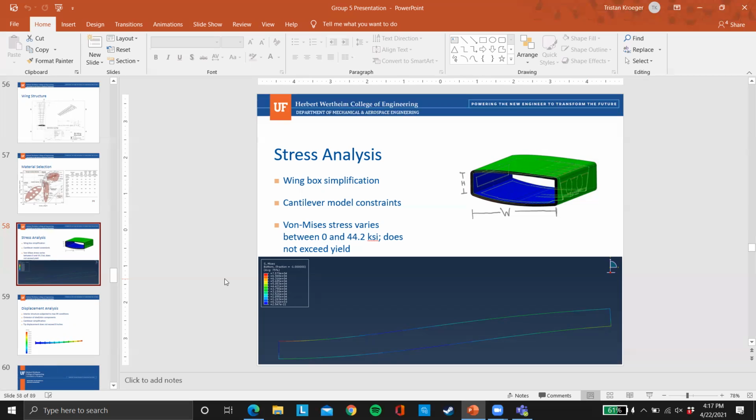Yeah. So now let's say this is the fuselage, this is a wing, right? And what I see from here, your Abaqus simulation should be like, okay, there's a lift, so it causes deflection upward, so the cross section of the wing should be box shape. Right. It is, yes, correct. And then for your simulation here in Abaqus, let's forget about everything else. What is the cross section here? It's one line on top, one line on bottom. What's connected?